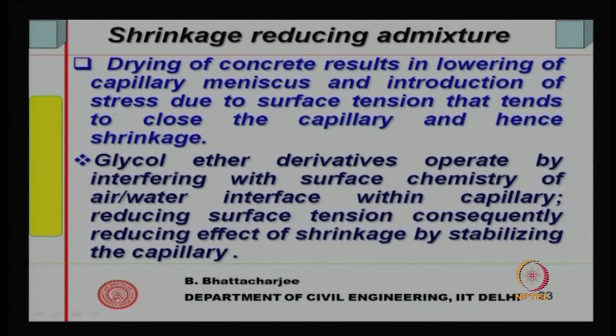Now, glycol and other derivatives, for example some glycol ether derivatives, operate by interfering with the surface chemistry of the air water interface within the capillary, thus reducing the surface tension and consequently reducing the effect of shrinkage by stabilizing the capillary.